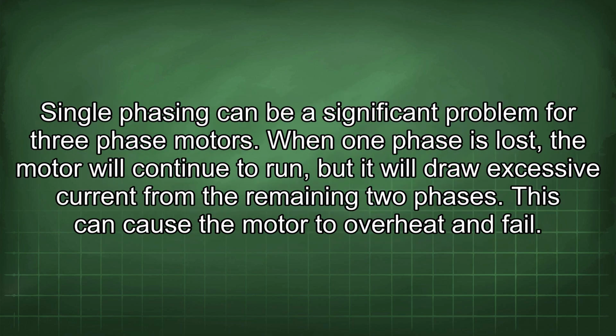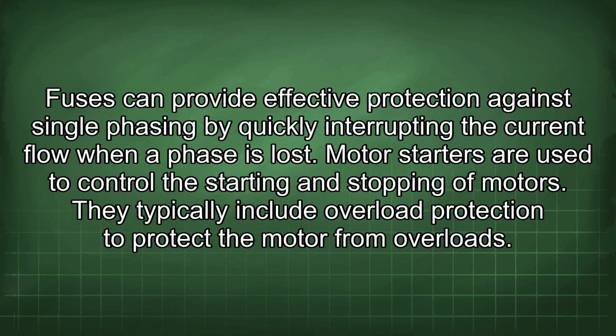Single phasing can be a significant problem for three-phase motors. When one phase is lost, the motor will continue to run, but it will draw excessive current from the remaining two phases. This can cause the motor to overheat and fail. Fuses can provide effective protection against single phasing by quickly interrupting the current flow when a phase is lost.